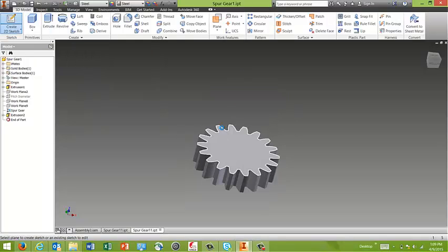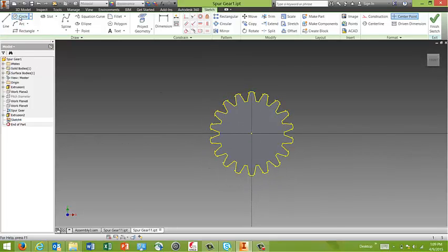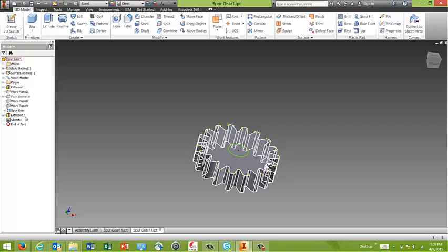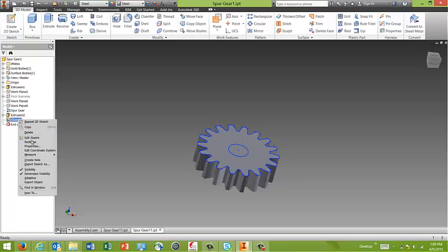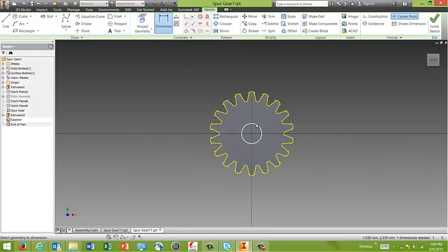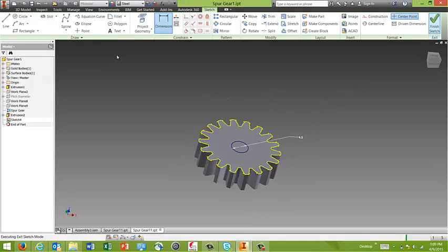Now what will happen is that a gear is usually attached to a rod, and for most of the rod sizes that we have, 4mm rod or 6mm rod, you can decide and draw your circle so that you can create. Now let me adjust it more accurately to 6mm or 4. Let's see, it's a 4mm rod, so what I'll do is I'll put a 4.1. Because I want it to be an idler gear, I want it to spin freely on the rod, so I make it slightly larger at 4.1 millimeters. Click OK.